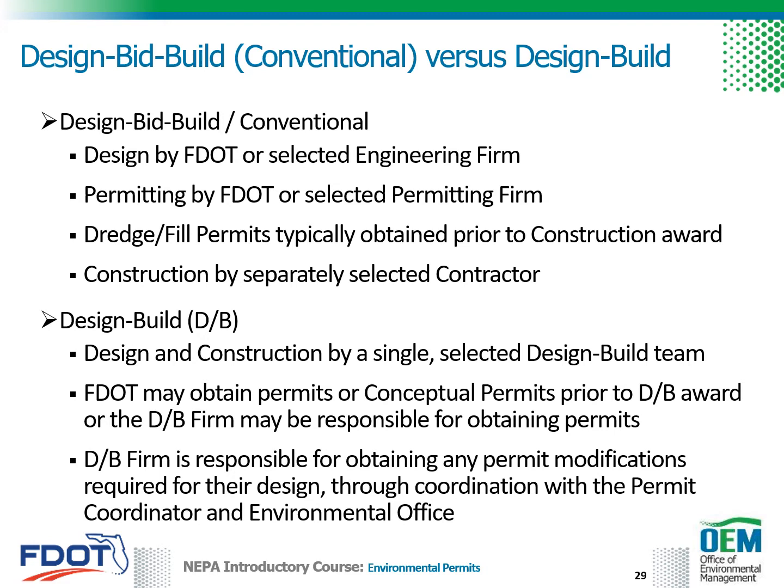The difference between design bid build versus design build processes from a permitting perspective is the timing of permit acquisition. Design bid build projects are awarded with completed permits, which are issued prior to letting. On design build projects, conceptual or construction permits may be acquired by FDOT prior to letting, but may be modified by the design build team based on design changes proposed during the alternative technical concept process. Otherwise, the permitting effort is assigned as part of the design build team's scope of services.